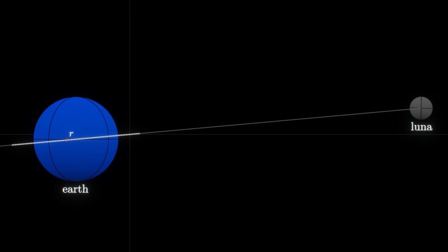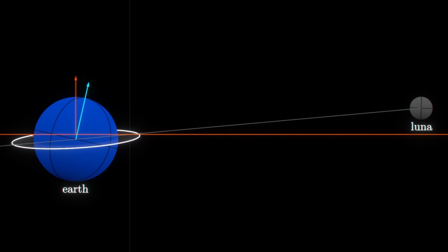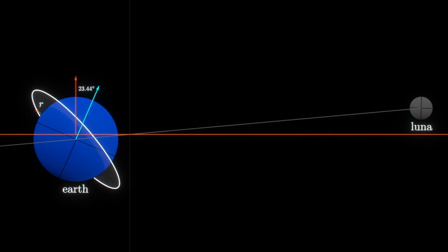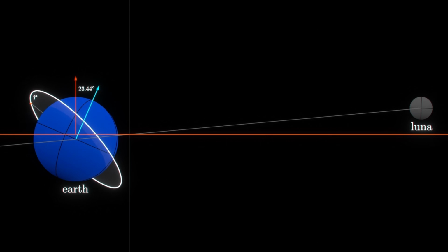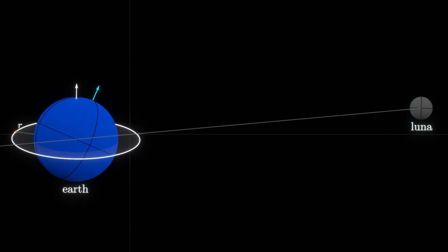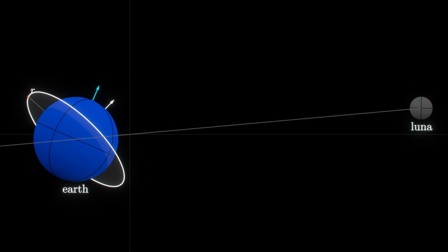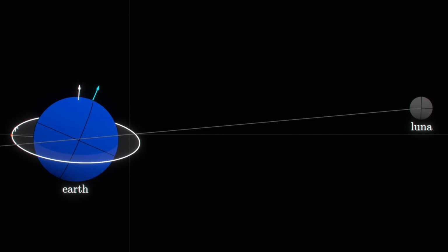For low Earth orbit, however, this is not possible, as nodal precession would quickly swing the station out of the lunar orbital plane, revolving it around Earth's polar axis, which is highly inclined at about 23.5 degrees relative to the ecliptic, which is the plane in which the Earth's orbit occurs around the Sun and is the universal solar reference. Accepting that any transit plan must account for nodal precession, how do we get the best time average delta V